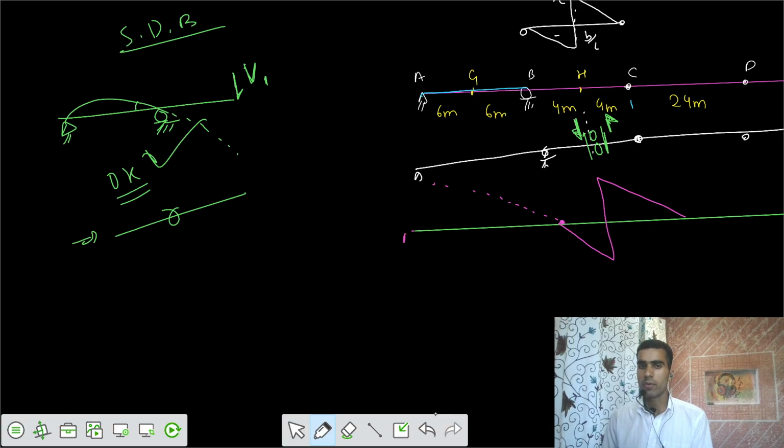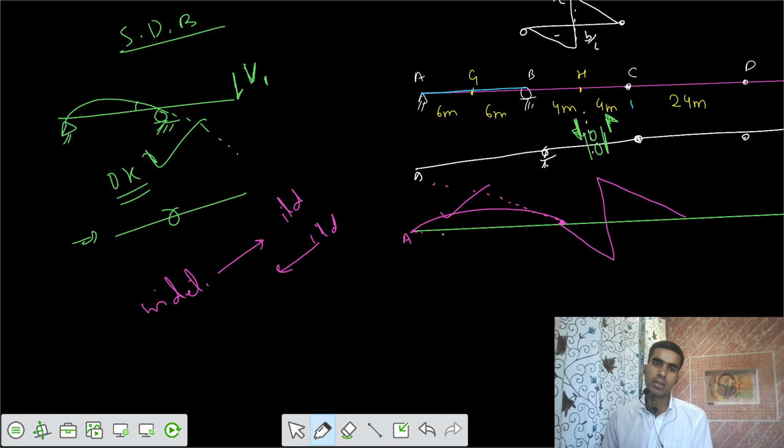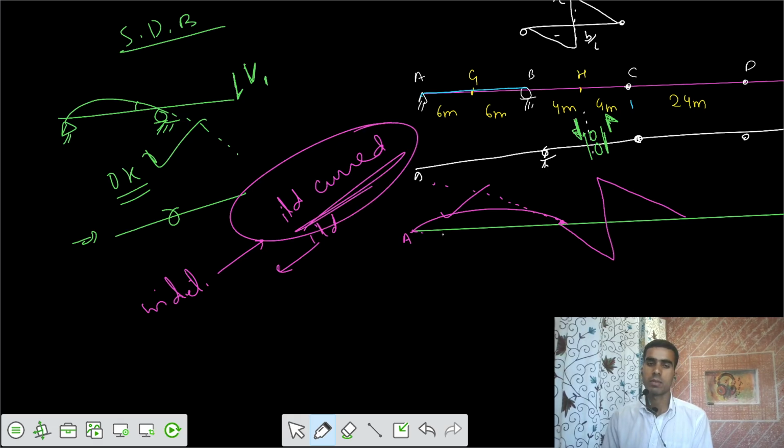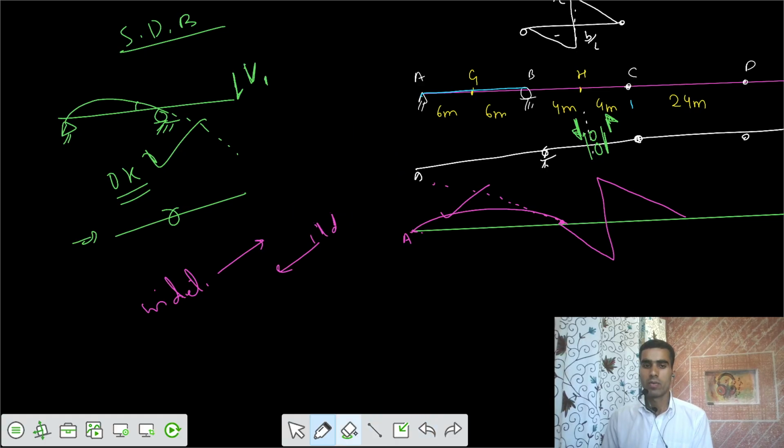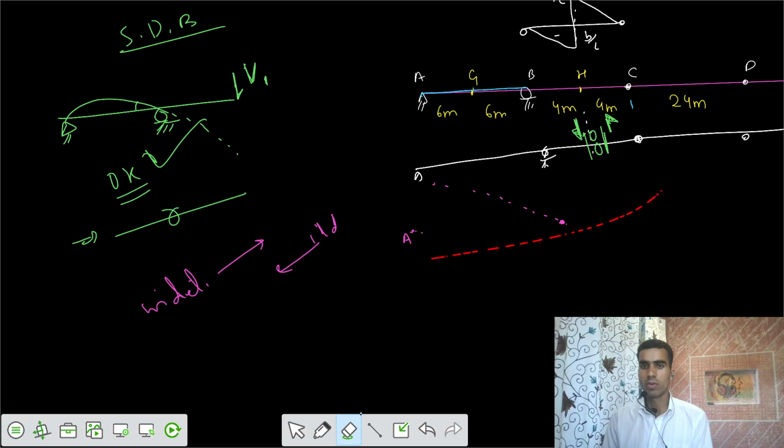If you want point A to remain at its location, but your structure is statically determinate, that means a curvature is developed, and that's valid only for indeterminate beams, because for indeterminate beams we draw ILD as curved line segments. So that's not true here. So we have to see what the actual variation should be.